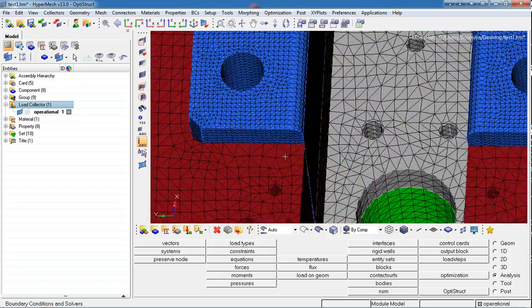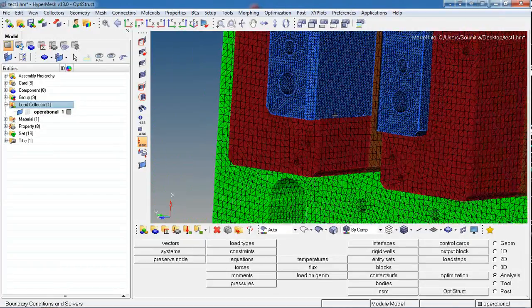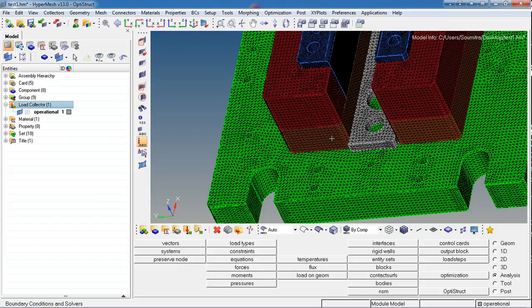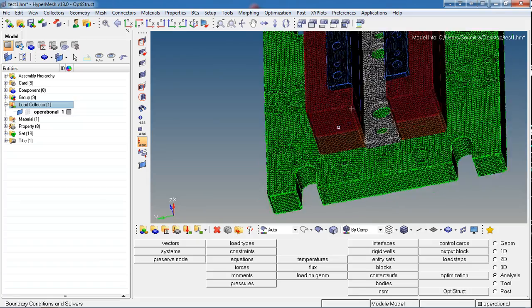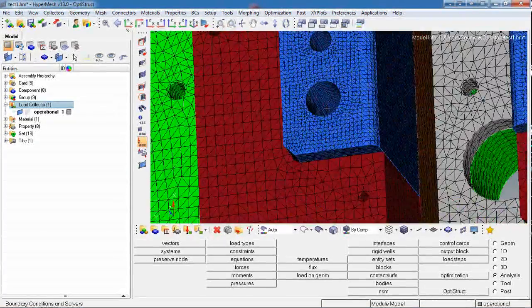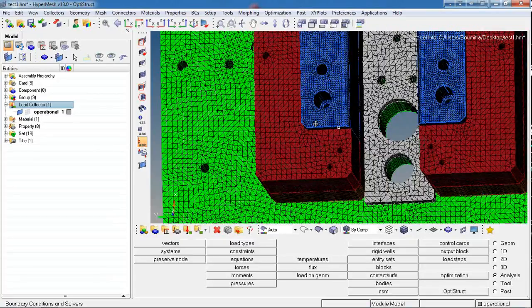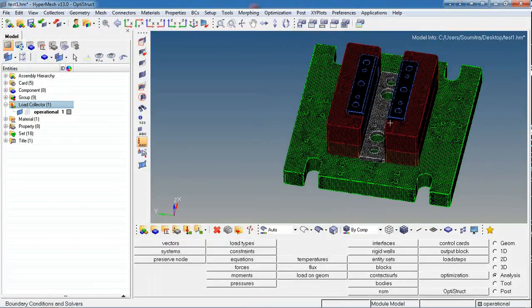We have established the contact relationship between these components: die block, die housing, die riser, lower shoe. They just have surface contact, but there is additional contact of bolting, because of the fasteners. We have constrained their degrees of freedom, so that also must be considered.